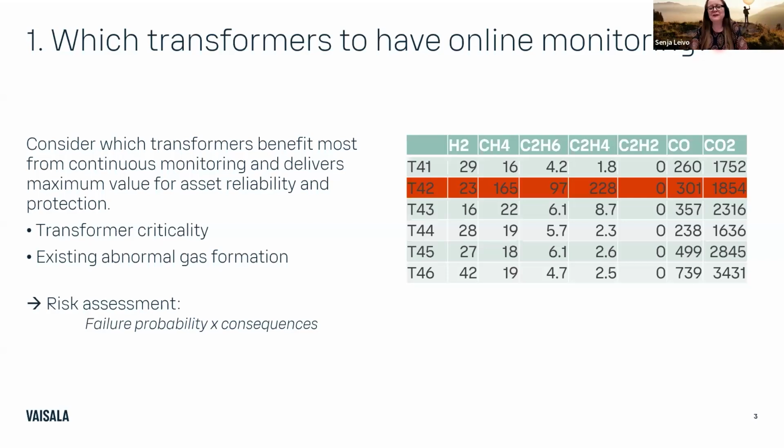That is a very good question, and a lot discussed when talking with people from utilities. In general, hydrogen is considered an early warning device, not enabling any diagnostics. And that is true in most cases. However, what I've noticed and discussed with many other people who are working with DGA is that there is a group of faults, thermal faults.